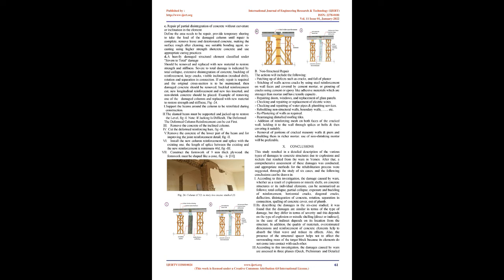The third step is to saturate the surface and then allow it to approach dryness just before placing the new concrete. In some cases, the concrete surface is prepared with epoxy or mortar to improve bond of the new concrete with the existing surface 9,10. Any exposed reinforcement should be cleaned of corrosion, oil, and dirt by sandblasting or wire brushing.